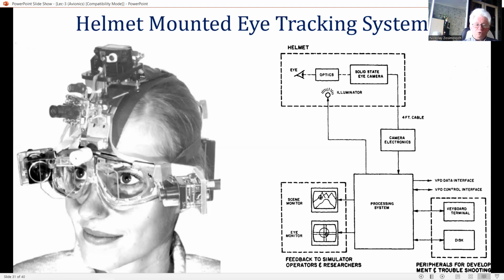The eye tracker also offers advantages in high G conditions when head movement is difficult, but the eyes can still move to look at a target. The basic principles of the eye tracker are very briefly explained a bit later, as an eye tracker can also be used very effectively as a means of data entry, a possible development in future cockpits.